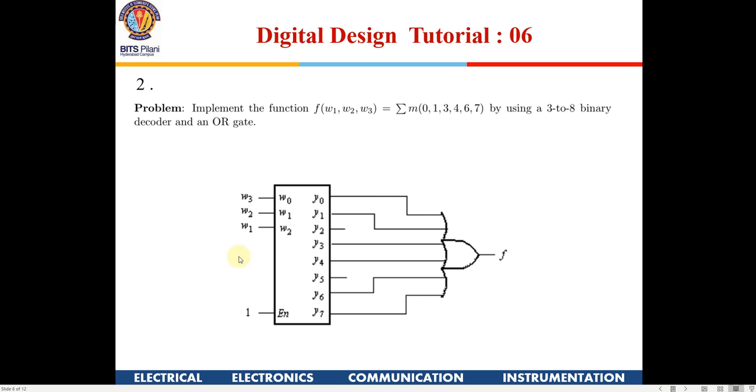Okay. Another variation to this problem could be when you are writing a gate or other thing, there could be an active low decoder also. Active low decoder means whenever you give say 000 here, normally everything will be 1. Only the bit which corresponds to the input will go low. So in that case, what kind of gate will you use? This is an OR gate, right?